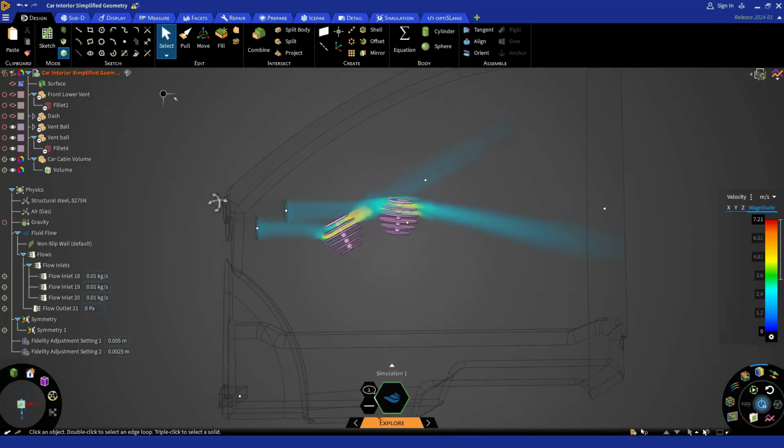By using cutter bodies, you just saw how we can Boolean the solid bodies from the bulk fluid region at the solver level, and you don't have to deal with any defeaturing or perform any extra operation like subtracting the solid from the fluid region.